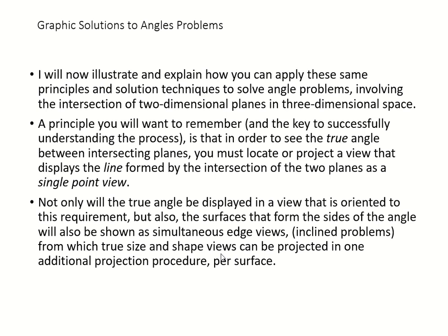So surfaces definitely matter, and we're counting on getting the edge views of these planes for that angle to be solved. Our final goal is to project the true size and shape in one of the additional projections or views.